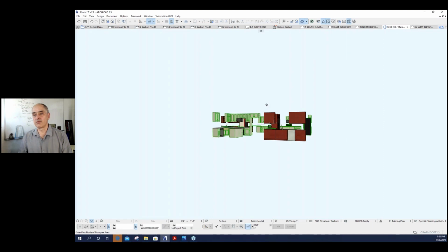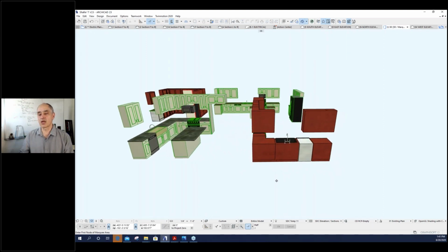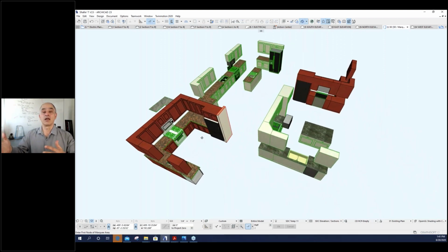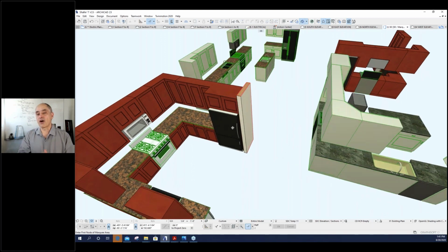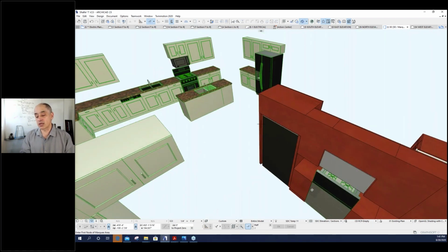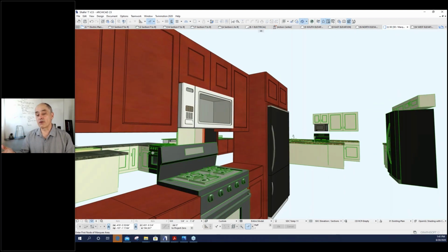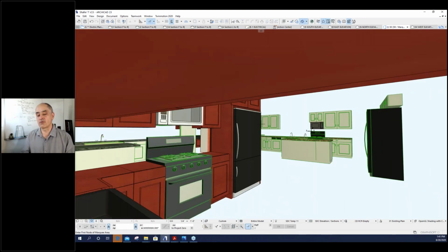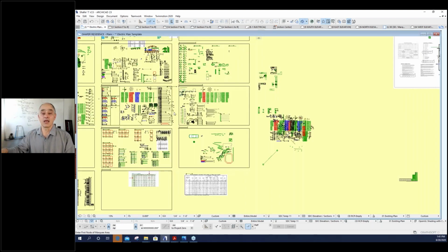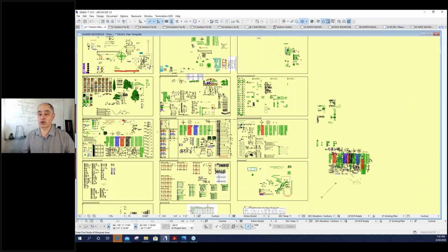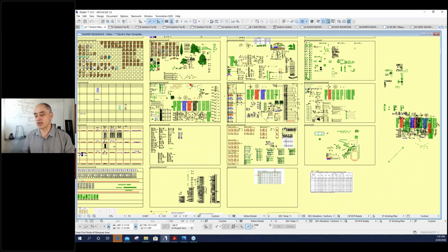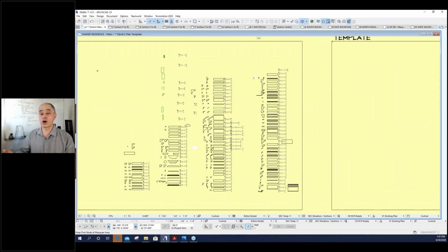I will give a couple of little procedural things. When you reference in an outside file, which we do in MasterTemplate, for example, where we have a whole kit of parts that is hot linked in, the file size of the actual project does go up. All of the data is in the project, but it's centrally managed. That's one of a couple of main advantages of the approach that I use: if you update the template, the next time you open that project or any project or start a new project, it has been revised. You've got more stuff in it or refined things, but the size does not change if you are linking it in.